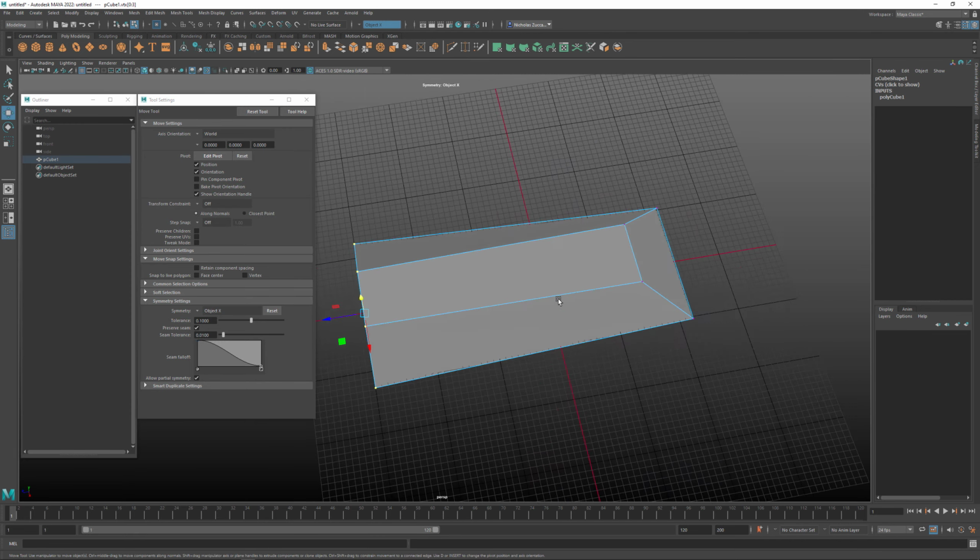Okay. So the other thing that we can do with this that I think is pretty interesting: select the object, and if you hold down Shift, and I'm going to hold down X to drag out that copy like that, if we hit Shift D after we've duplicated and moved and translated the object, we can keep duplicating with that same amount of movement and translation. So I'm going to select this and get rid of that right there. So you could tell with that one, just moving it along.